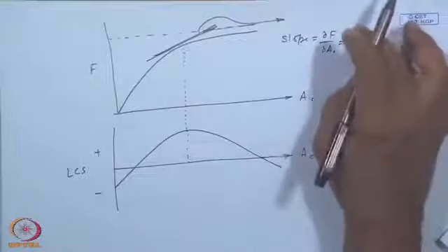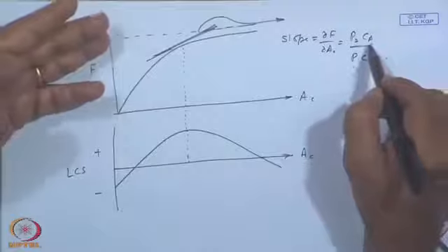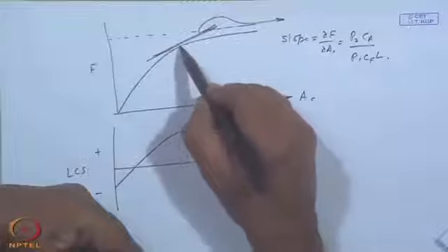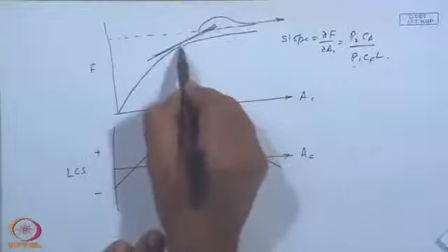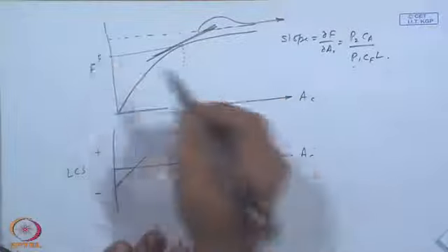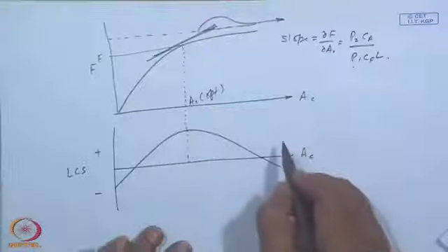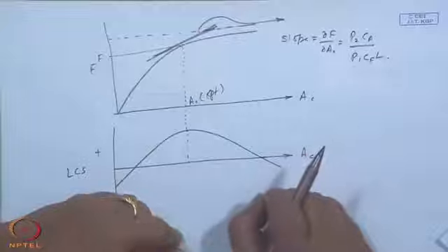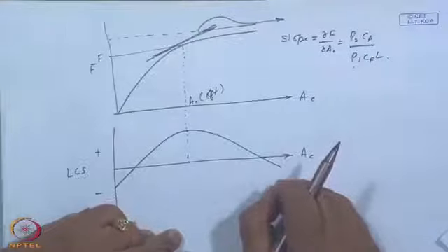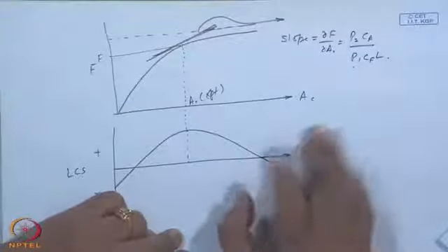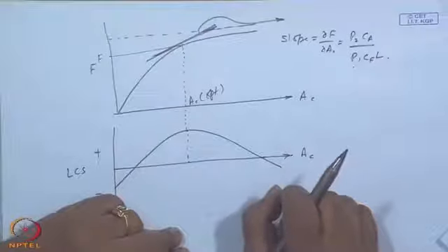So, you will find out this number and draw a line with the slope being equal to this number, and wherever it cuts, of course, I have drawn it a little away just to be clear. So, that is where my optimum F and AC lie. So, the idea of the analysis is that you find out that the life cycle savings is a maximum, where your load fraction delivered need not be 100%, but the returns per rupee investment is the maximum.